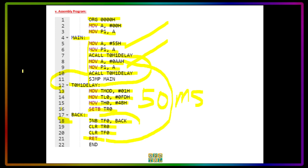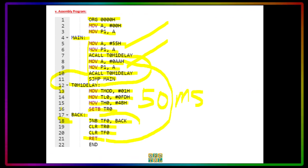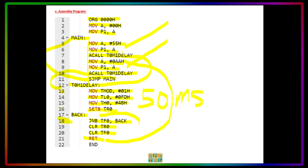And that's it. And then finally, we have to go back to main. So SJMP means short jump in assembly, although you can also write JMP if you want. So SJMP, it will go to main, and it will repeat the process again and again, or repeatedly or continuously. So there you go. This is the assembly language program for our problem.